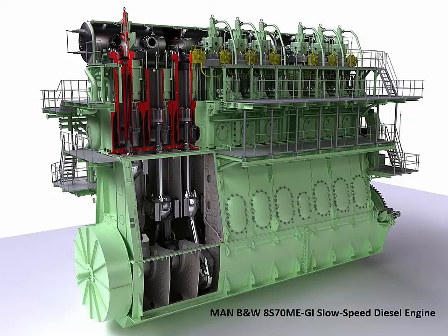So when you're talking reversing engines like these big slow speed ones, when you're maneuvering, each time that you change direction, each time you go from ahead to astern, you're going to have to stop this engine. Also, at dead slow, the minimum speed is typically around 6 knots, which is too fast, say, to approach a dock. So the mates will have to start and stop this engine to control speed of the vessel.